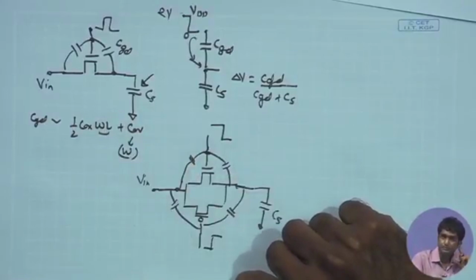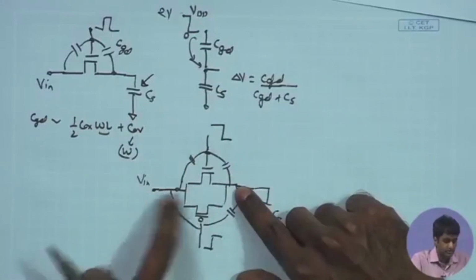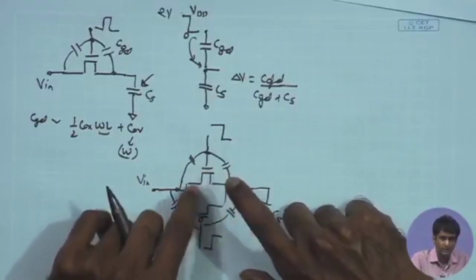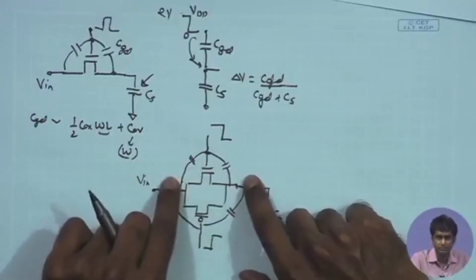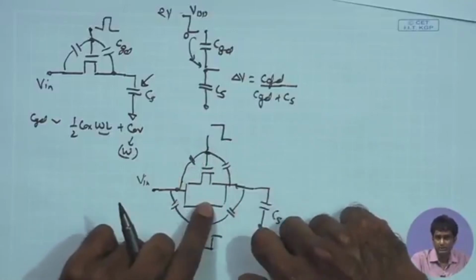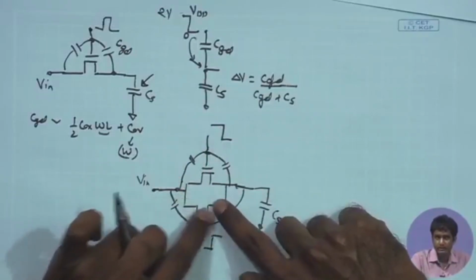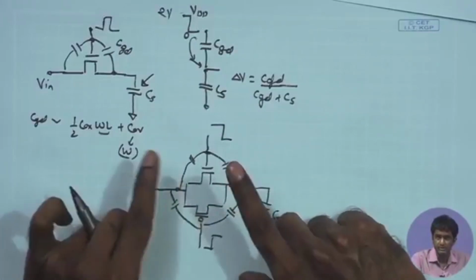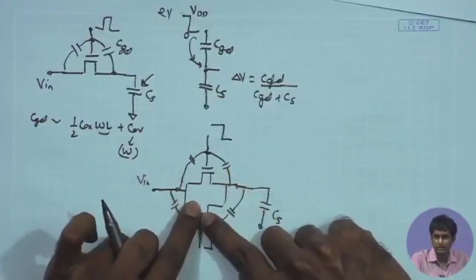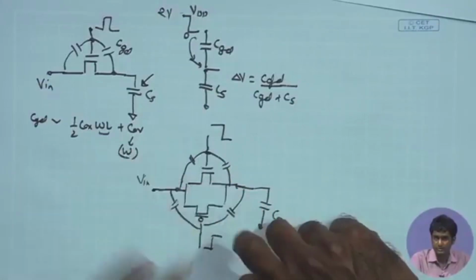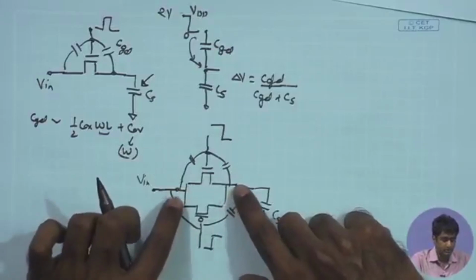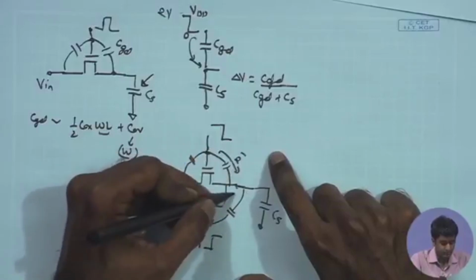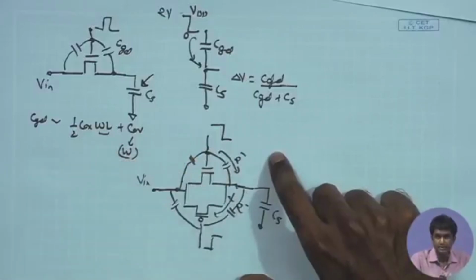Likewise, if I talk about the charge injection for the NMOS, as we said, it is going to inject negative charges, right. Whenever it is turning off, the electrons which are forming the channel of the NMOS will be injected on the opposite side. PMOS has holes in the channel, right. So, that effectively means vacancy of electrons. So, when the PMOS turns off, the holes get injected, physically, of course, electrons get injected into the PMOS channel to kill the channel. As a result, the NMOS is going to dump electrons, whereas the PMOS is going to sink electrons when the channel gets off.